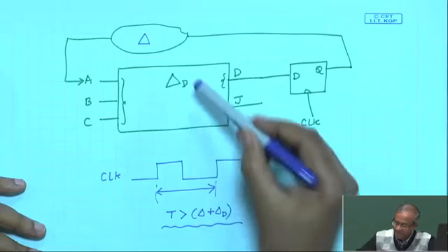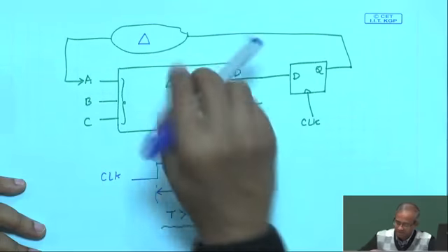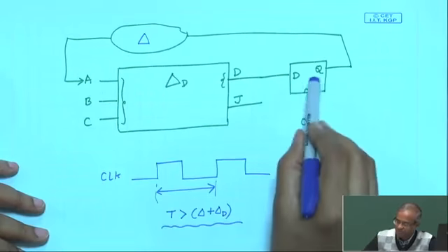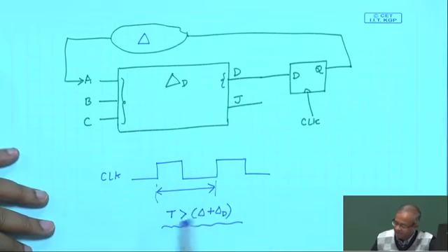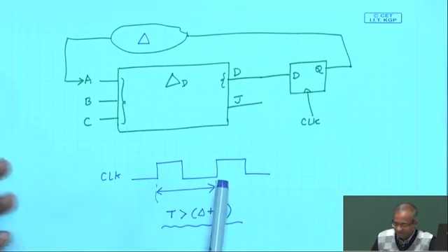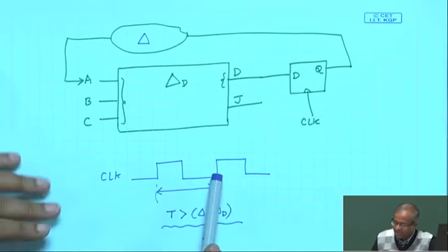So, if you do a static timing analysis of each of the circuit blocks between the flip flops, then you can have a very fair estimation of the worst case timing delay between clock pulses, so that you can know, at least to a fair degree of accuracy, what is the maximum frequency of the clock that you can apply, right.